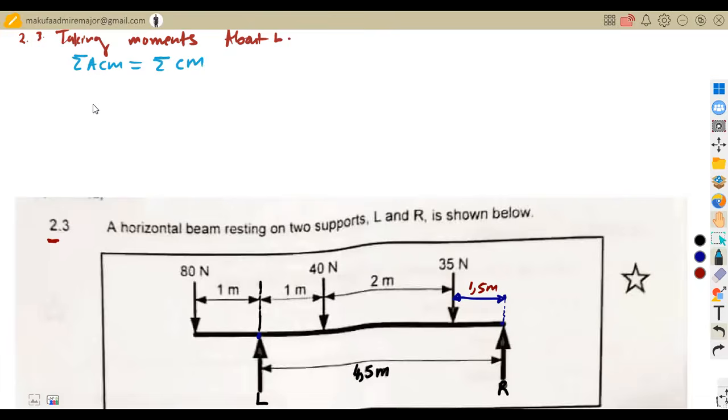As for me, it's best to start with the side of the one that I'm calculating, but it's one and the same thing, all right? So R is going in anti-clockwise, but we need the sum of everything that is going in anti-clockwise back to L. So let us have force times distance, which is R times the distance back to L. What is the distance there?